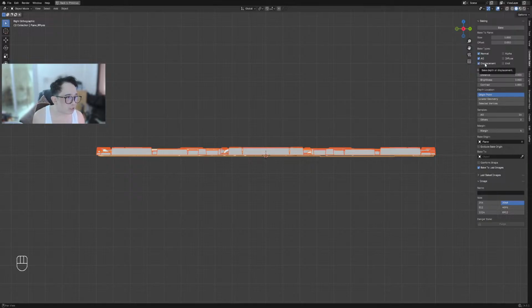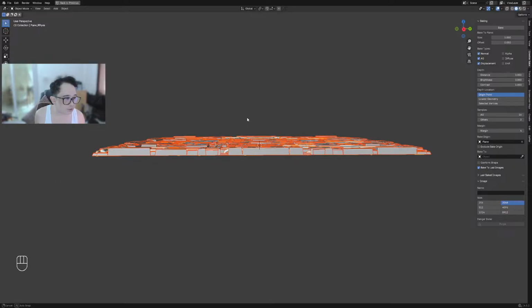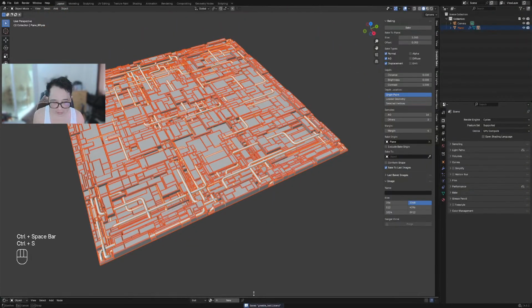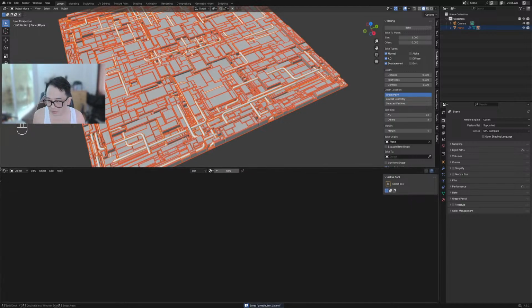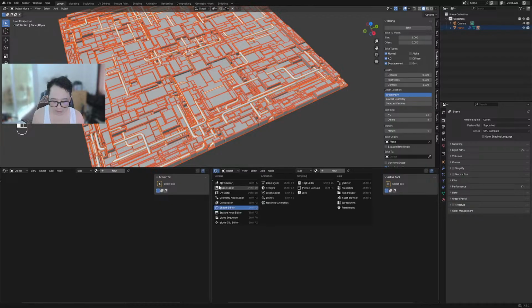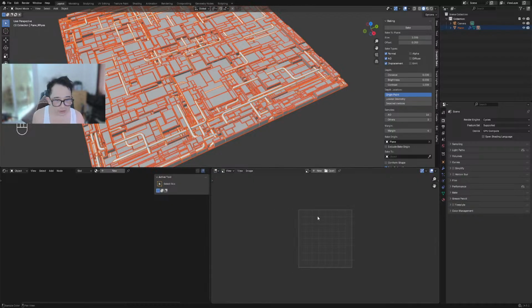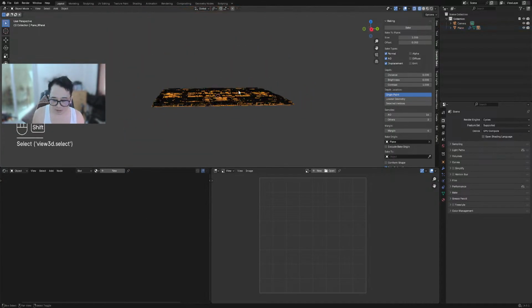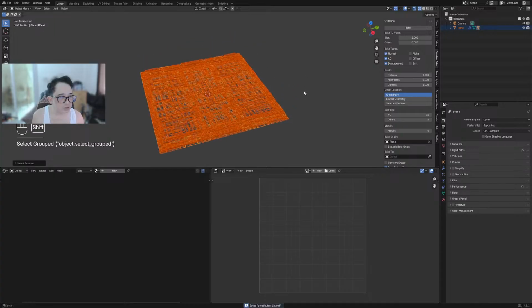So with displacement, we can also use it as textures, or to darken the base texture. Okay, so let's go ahead and bake. I'm just going to open a window here and then go to image and select all these meshes here to be baked.